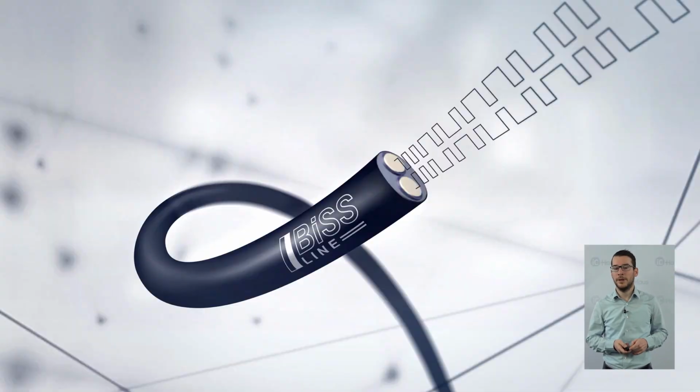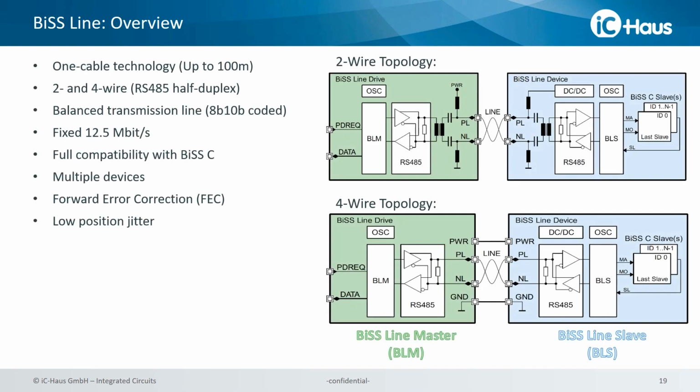Okay, now we go on to BiSS Line, which is our one-cable technology for the BiSS interface, which enables a robust power and data transmission over just 2 wires, over transmission lines of up to 100 meters. On the right side, you can see 2 different topologies. One is the 2-wire topology, which requires additional coupling elements for modulation of the power and the data signals. And one is the 4-wire topology, where we do not have these coupling elements, but require additional wires.